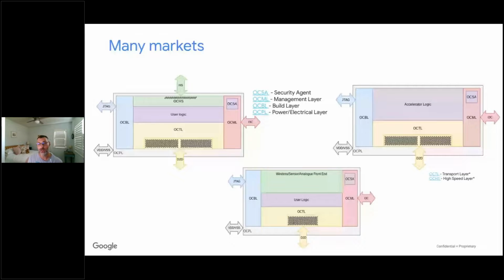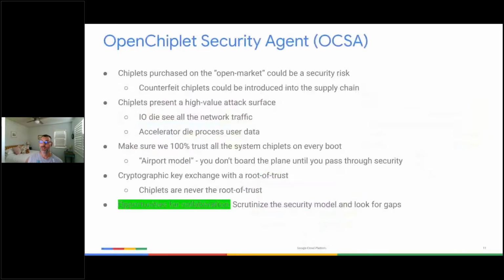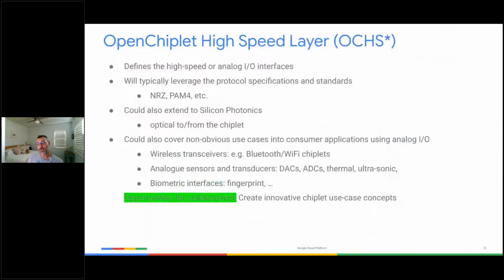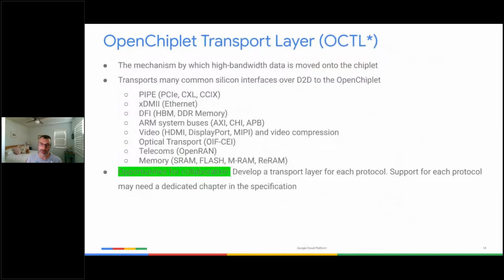Your CPU system could see the chiplet as just another memory mapped part of the system, or if this die was full of SRAM, the CPU would want to see that within its flat address space. So those ARM buses are one way to achieve that. There are open source system buses available as well.